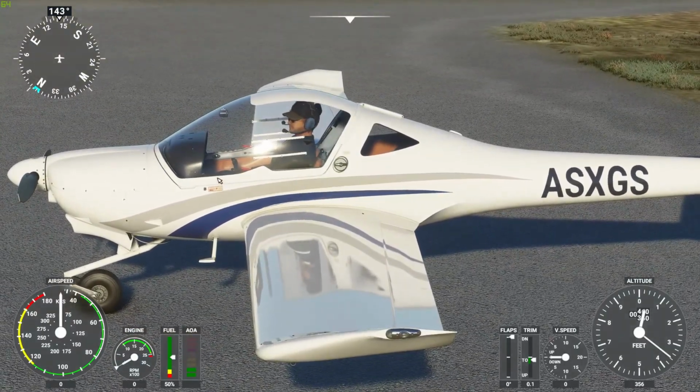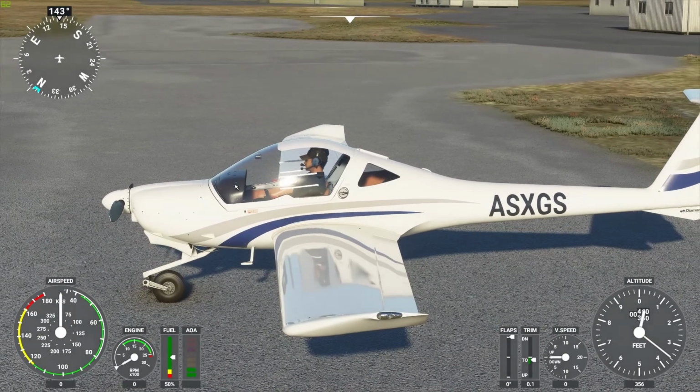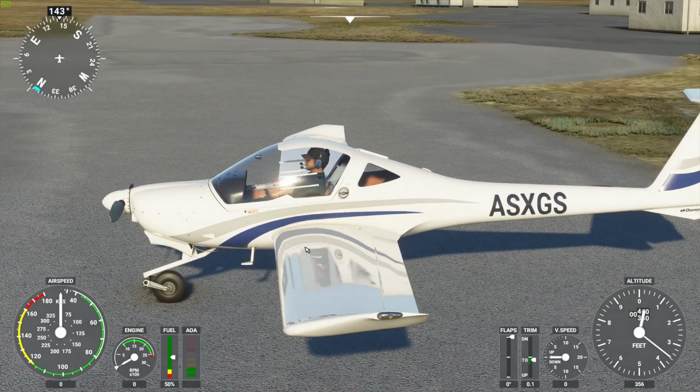So that's about it. We can see we have good visibility, particularly out the front here, but with the low wing, the pilot is sitting kind of on top of the centre of lift. If you think about looking at the aerofoil of the wing here, the lift is generally, if you could select a point where the lift is sort of balanced, it's going to be in about this position here. Where the pilot is sitting in relation to that is going to determine a bit about how the aeroplane feels to fly and its stability. So that's about it from there.